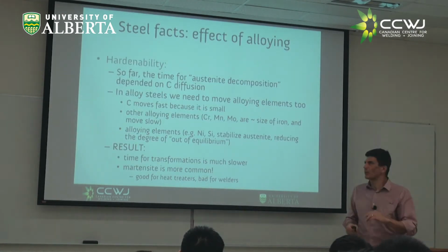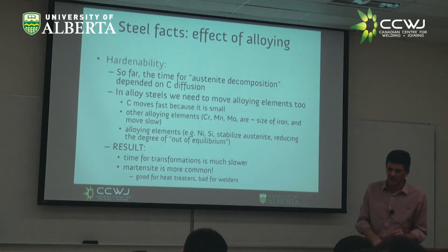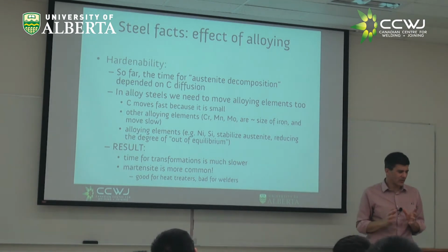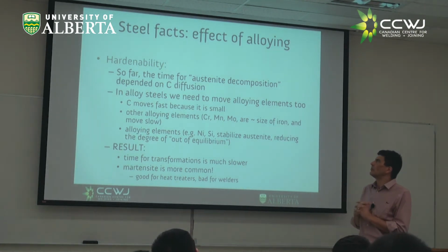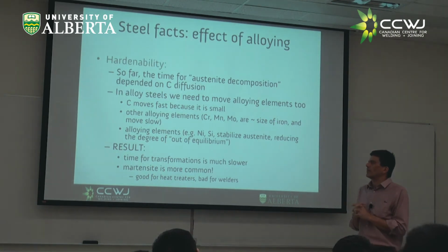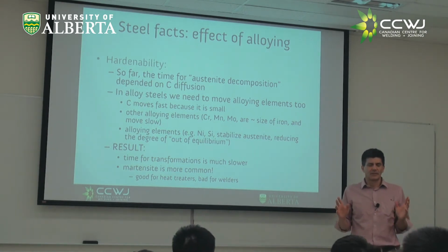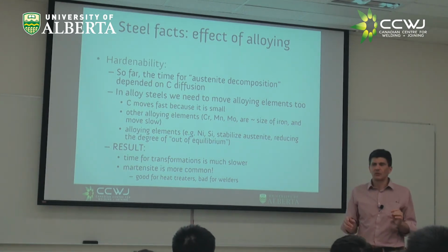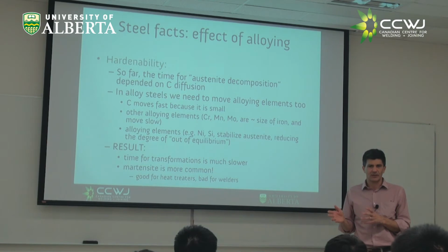Still, I want to tell you one more thing about theory. Something called hardenability. And it's an interesting concept. Martensite is hard, but to get martensite, I needed to cool very quickly, because if I don't cool quickly enough, it's going to start transforming on me.